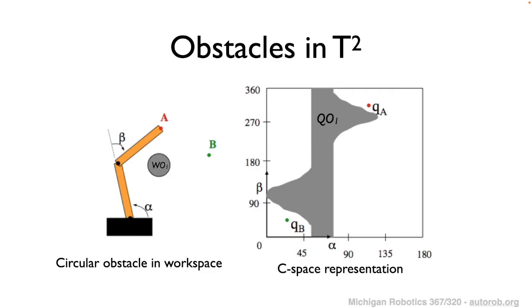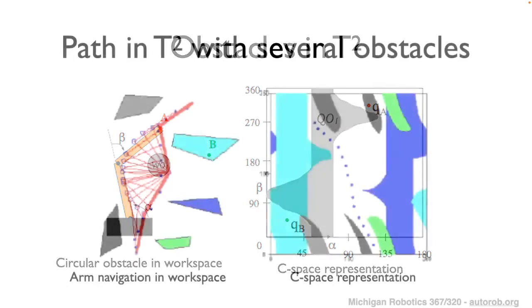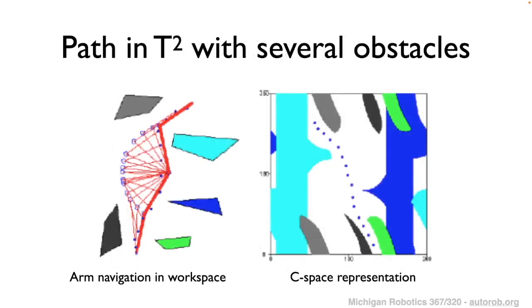So you can see that it takes a very, very different geometric form once that obstacle is represented in the configuration space. And if we instead were to use these oblong shapes, these parallelograms and triangles, you can see that once they're expressed in configuration space, once again they take very, very distinct forms that are very hard to reason about when it's in workspace, how those are going to transform into configuration space. And so that's one of the reasons why expressing everything in configuration space for our motion planner can be a nice approach.